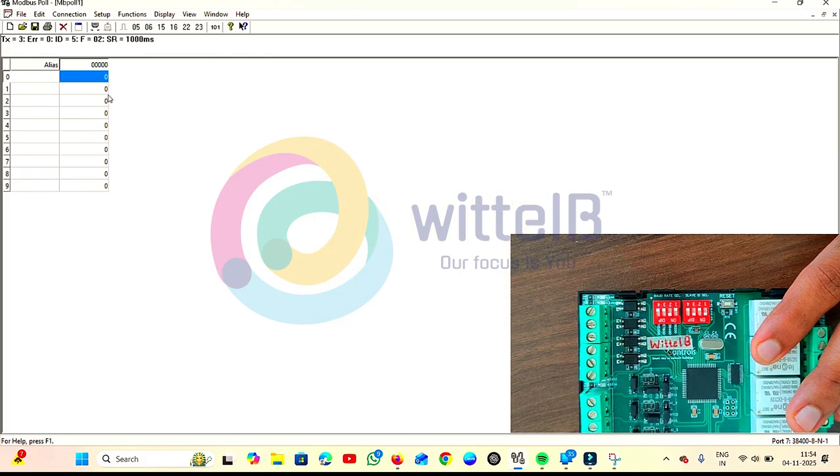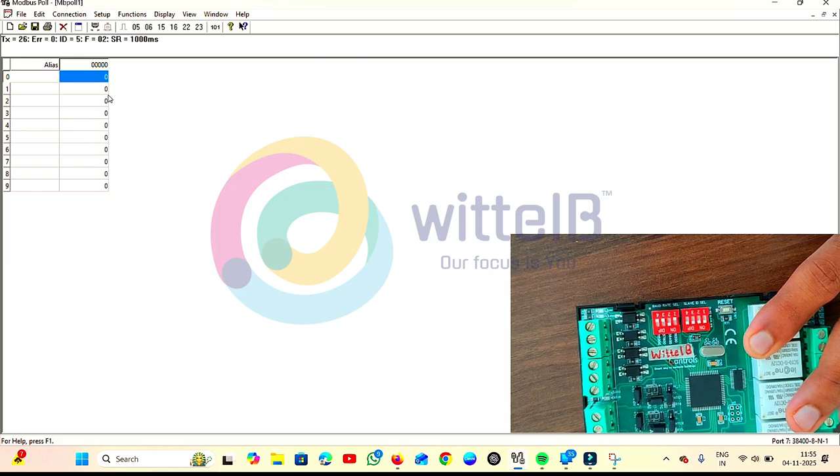See, here the board has connected properly with the new configurations as a slave ID 5 and the baud rate 38400. So now I need to set the baud rate as 57600 and the slave ID will be 15. If I need the slave ID as 15, then I need to hide all the slave ID pins. That will be 15.